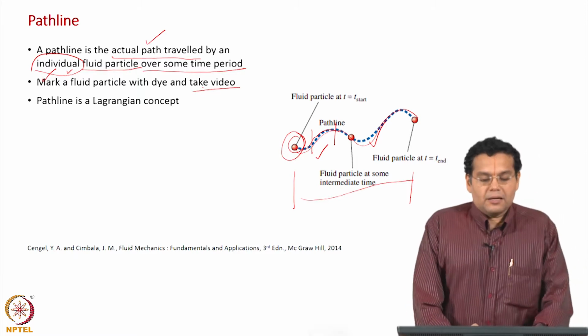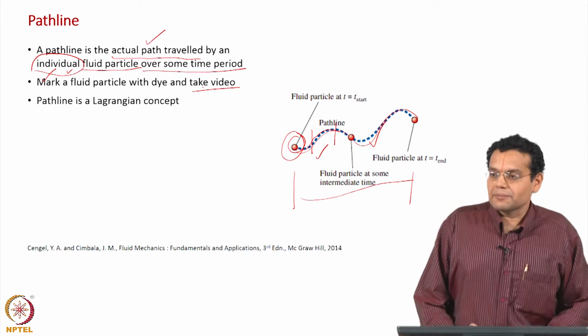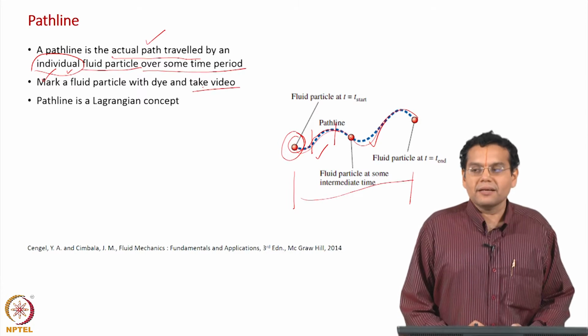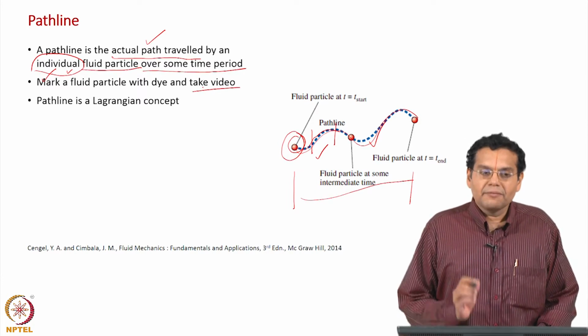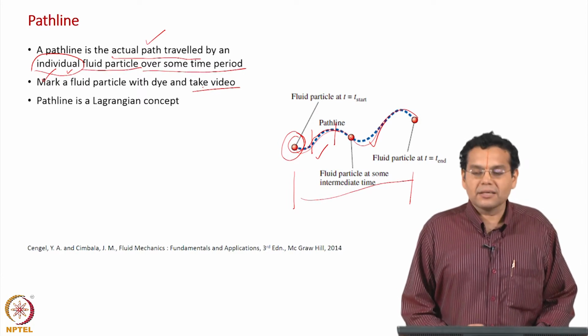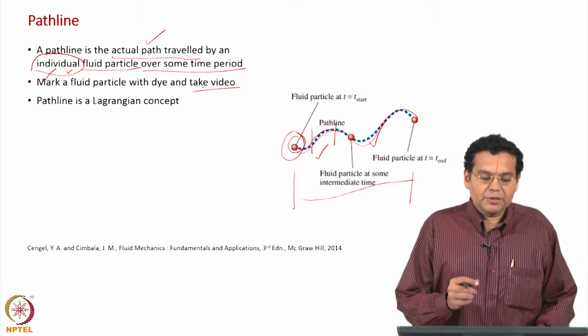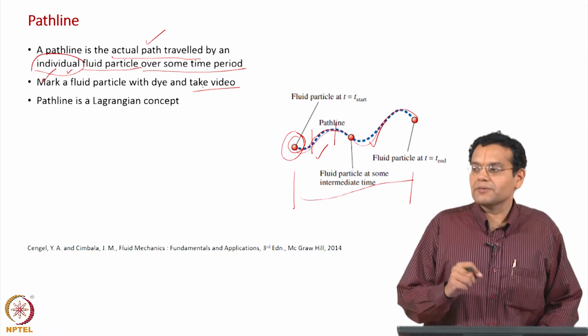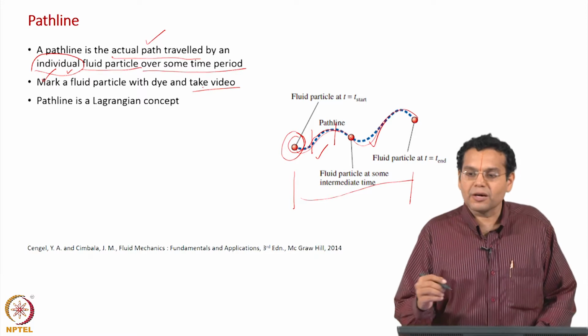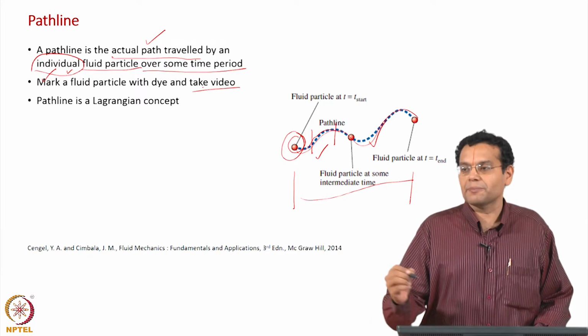Yeah, path line is a Lagrangian concept. By the way, I have discussed, it should be very clear that it is a Lagrangian concept. When we discussed the Lagrangian concept, in fact, without using the term path line, what did we say? We identify a particle and follow the path followed by a fluid particle.